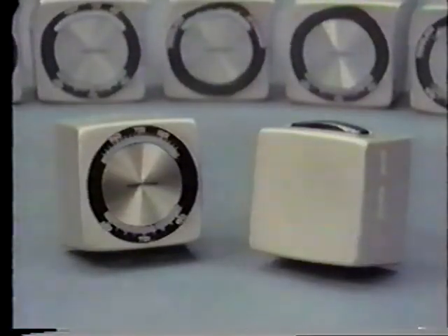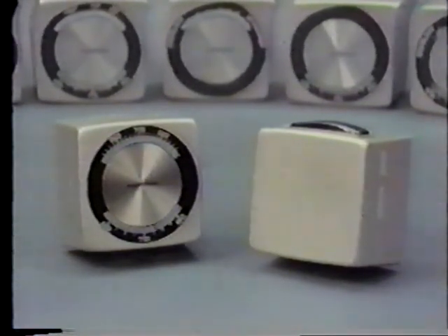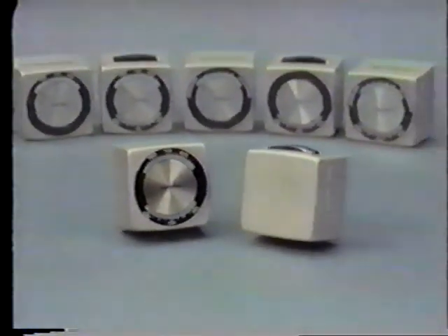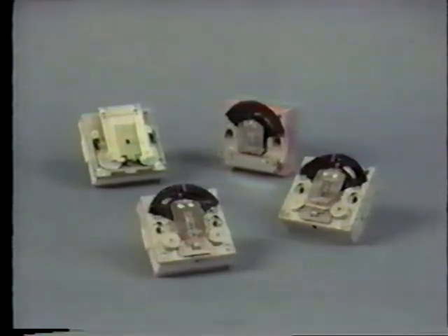There are many different types of thermostat covers available for commercial applications. Most common of these is the blank cover with a concealed set point adjustment, and a full dial model with thermometer and exposed set point adjustment. There are a number of other variations of thermostat covers that may be used to meet the requirements of a given application or the specifications of an architect or engineer designing the control system. There are many variations of thermostats available, and you've seen just a few, namely the two-pipe single pressure devices.